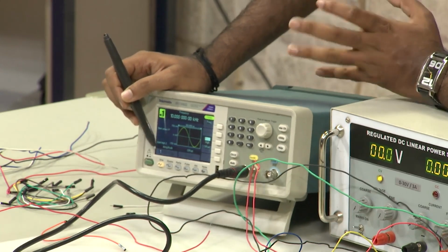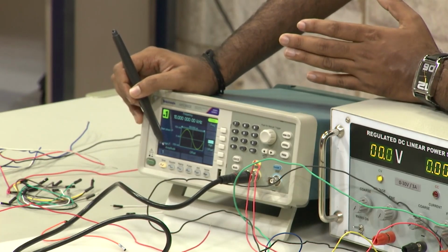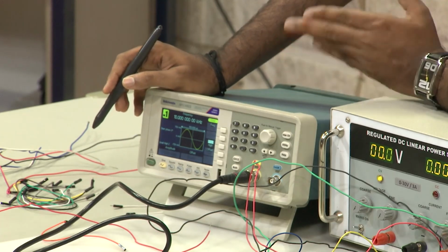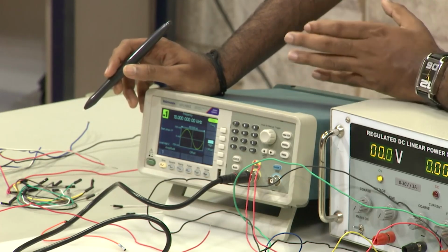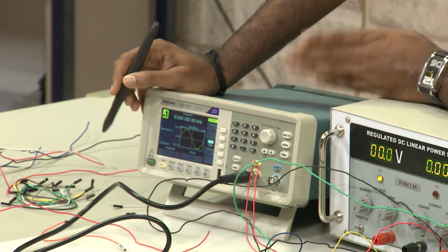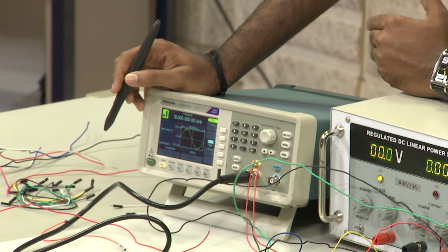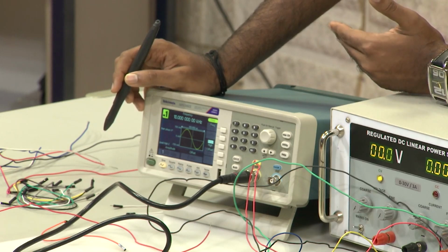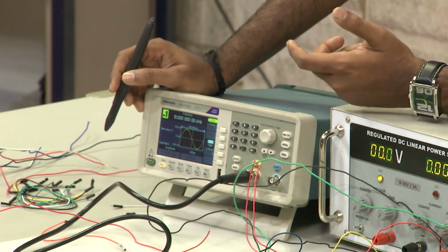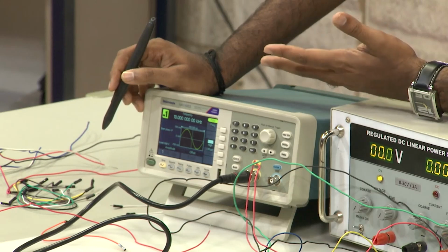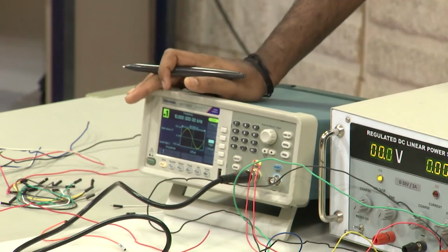Just like the previous experiment, we will see the output waveform and its voltage level. I will keep increasing the input voltage and see where the output saturates. Thereby, we will calculate the range of this configuration and compare it against the range we saw last time. If you remember, in the previous experiment a sinusoidal wave of around 12.5 to 13 volt peak to peak, or 6.5 volt peak, was causing saturation. So the input voltage range was 0 to 6.5 volt. That is all. Now let us see the oscilloscope.